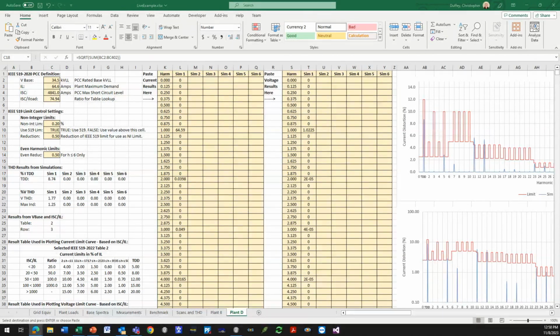We base the method on superposition, and we say that it holds so long as the circuits are linear, and then we move to the Fourier transform. However, we did not go through the nonlinear elements of the system, such as the magnetization core of the transformer. That is exactly correct. For a harmonic analysis, in the majority of cases, you're not simulating the third harmonic being produced by the magnetizing of the transformer. We're going to assume that the transformer is a linear element.